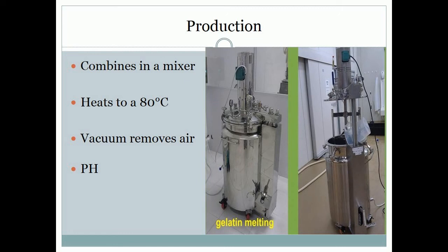Heating of the inner tank liner is done with circulating hot water. This means fast heating, good thermal insulation performance, improvement of the quality of the gelatin and acceleration of the gelatin melting time. During its working process, the machine will suck air and moisture from inside of the tank, leaving a 92.4% vacuum for about 6 hours. pH is checked every 10 minutes. pH is in the range of 3 to 8.5, usually 5 at 60 Celsius.